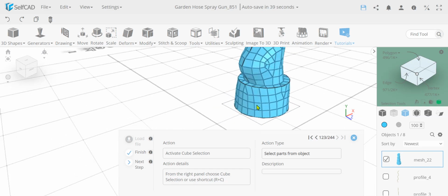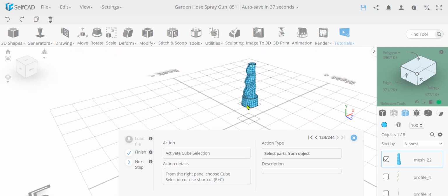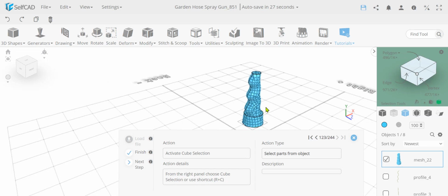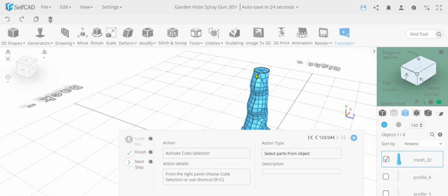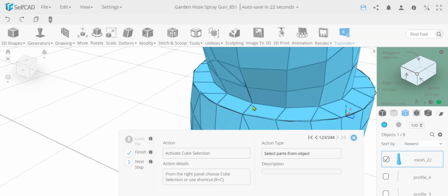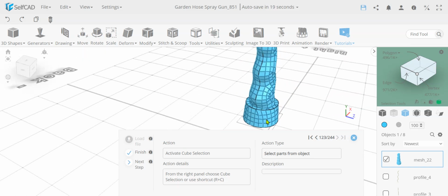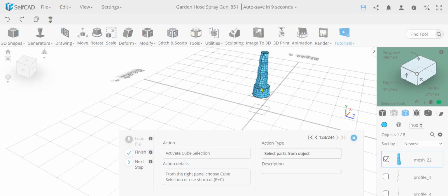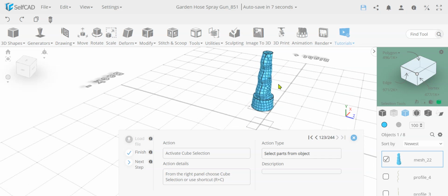And the second condition is they must go through all profiles. You cannot make a rail just on two profiles. However, and this is something unique to SelfCAD, SelfCAD will automatically fill in rails when they are simple. So the designer over here is drawn only from this profile onto this profile over here, and technically you cannot see it, but what SelfCAD has done is fill in straight rails over here and over here, because otherwise this wouldn't work. So SelfCAD is doing that automatically. So it's sometimes easier, you can skip the remaining ones, but SelfCAD will not be able to fix it if you skip something in the middle.